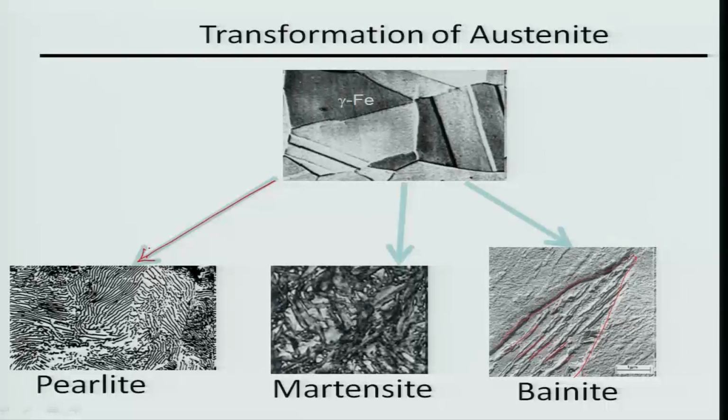austenite transforms to pearlite. As you know, austenite is an FCC solution of carbon in iron, which is stable at high temperatures, something like above 727 degrees Celsius, which is known as A1. As you cool it down below 727 degrees Celsius for eutectoid steel, you will get a phase mixture of alpha and the cementite, which forms a lamellar morphology.